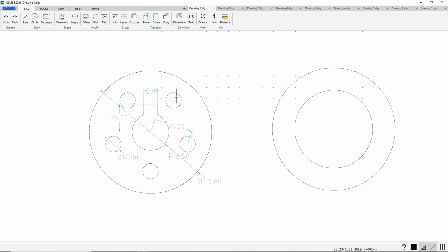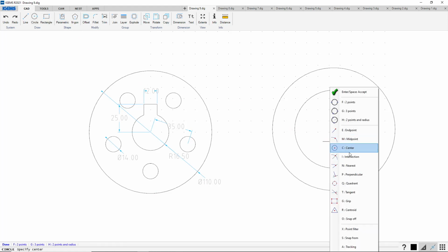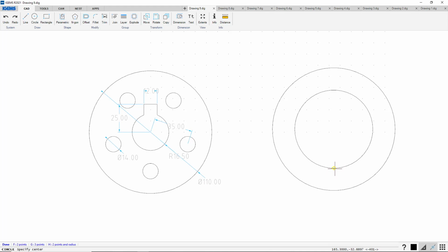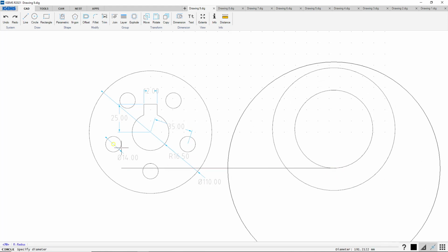And when you see a pattern like this, I like to go for this circle, because that's in some kind of a center line through this part or through this geometry. So I'm gonna draw that circle. So I'll choose the quadrant of this, and the diameter is 14.